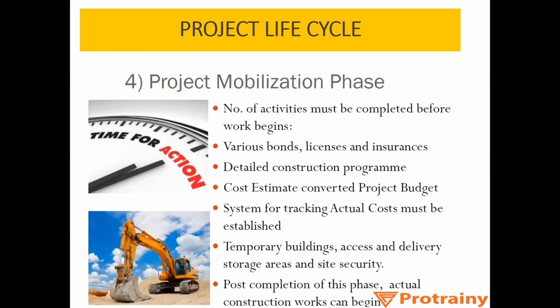Then finally the project mobilization phase, that is once you have finalized the contractor, now you will sign a contract document with him, and you will ask him to mobilize at the site, that you should come and start executing the work. So he will require some 10 to 15 days, which may vary up to 18 to 20 days, to bring labor to site, to bring heavy equipment and machinery to site, to bring all the engineers, to set up his office, to set up his labor colony, all those things. So a number of activities must be completed before the work actually begins.